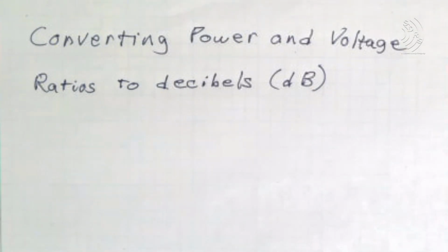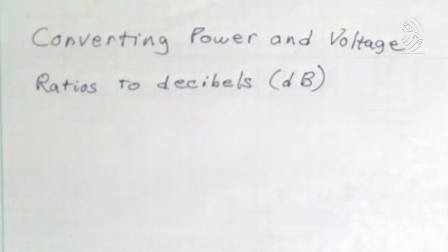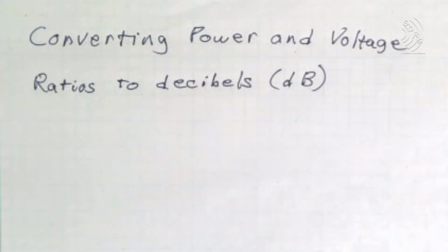Once these numbers are expressed in decibel form, they are much more convenient to use in calculations, because in decibel calculations, addition replaces multiplication, subtraction replaces division, and multiplication replaces the operation of raising a number to a positive or negative power. Decibel values are moderately sized, positive and negative real numbers, typically, if not always, between negative 300 and positive 300 for RF applications.